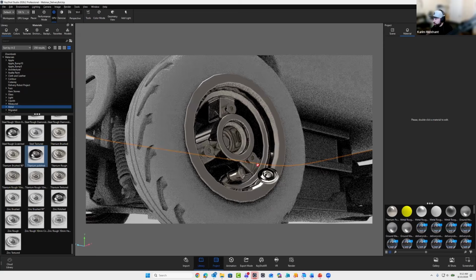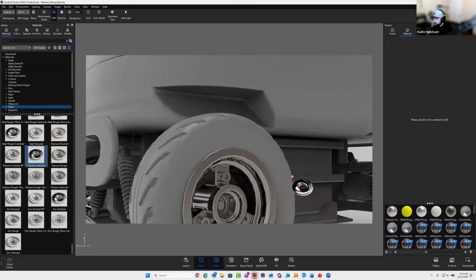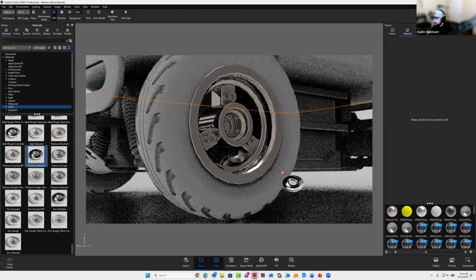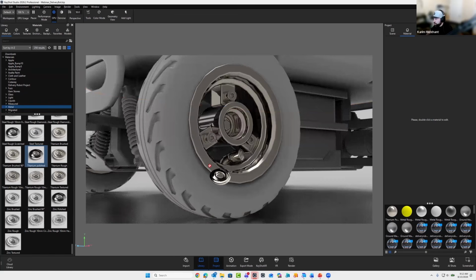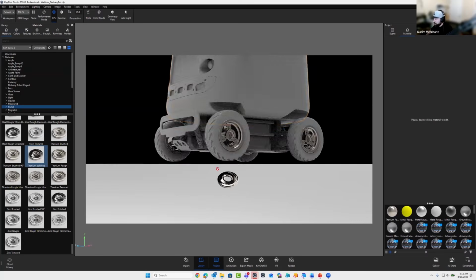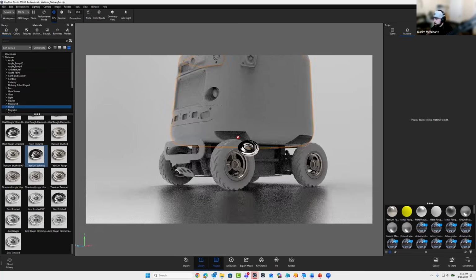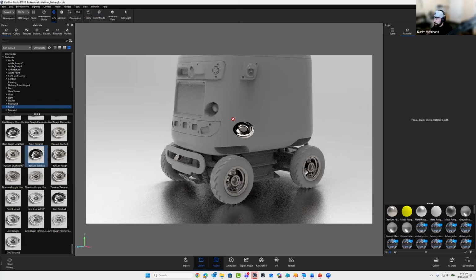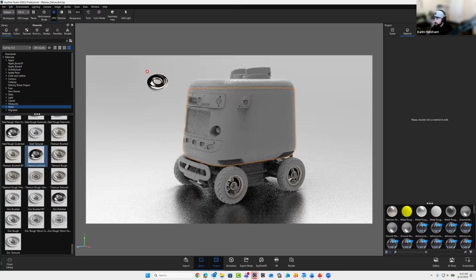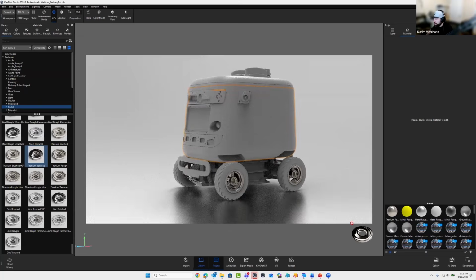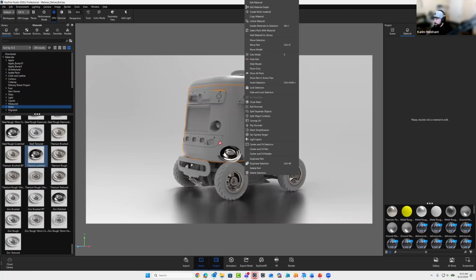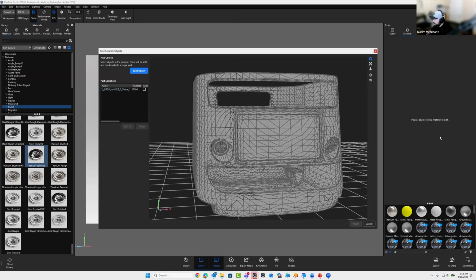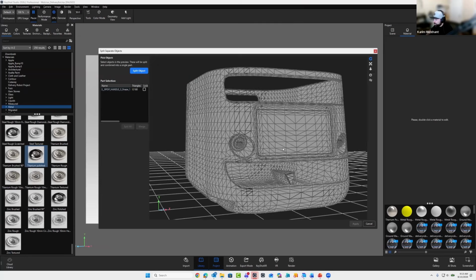And you'll notice when I open this window, we have that body. And when I select the body, it's isolating the body and it's recognizing that there's other components here that are actually separate bodies. In this case, we want to split this screen in the front, so I'll select that. We've isolated the screen. I'll hit split object, and then I will apply that split. And now when I select it in the scene, you'll notice that it is independently highlighted there, and we actually have a separate line item for it.